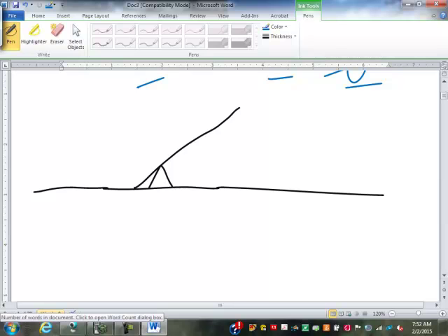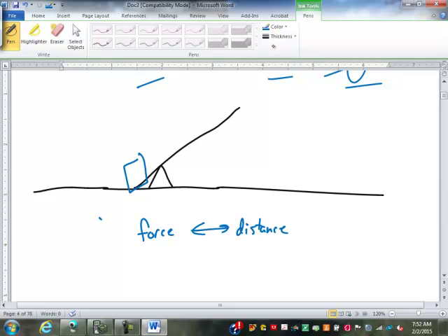So anyway, mechanical advantage is trading weight or force for distance. So like here, let's say I have something rather heavy that I want to lift. The way this is set up, if I push down right here, I'm going to lift that relatively easily. But I may have to push this far, and over here, it's only going to lift up about that far.